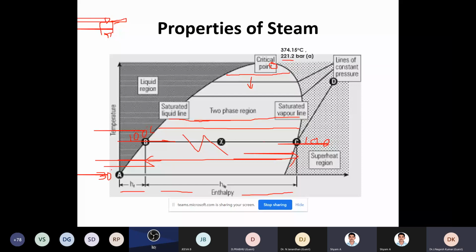See, this latent heat is required basically for heating purposes. When you want to heat something, the steam will condense, it gives up this latent heat and heats the substance. But in the case of power plants, we don't need any heating. We want kinetic energy. The enthalpy of the steam has to convert to kinetic energy to rotate the turbine. So there's no heating involved in the case of steam power plants.